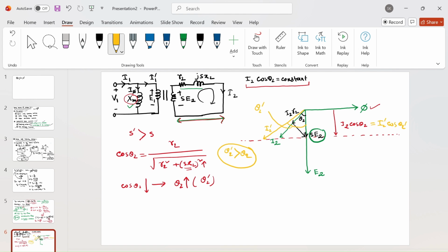So now it is clear, like let's say this was your torque slip characteristics of induction machine, and you had a constant load torque, and you made some changes. Let's say initially this was the operating slip, maybe now you have made some changes and your operating slip is here. We have to analyze the graphs, but approximately the graph will cross from this particular point.